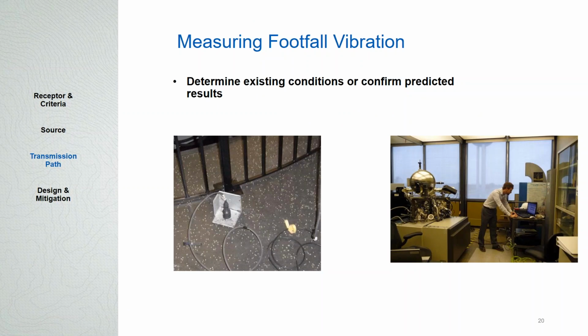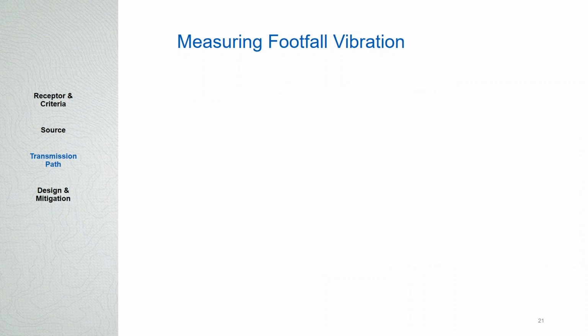And so with that, we show up on site. There are vibration sensors that can measure very, very low levels of vibration, well below the threshold of human perception. Hook a vibration sensor, an accelerometer, up to the data acquisition system and just measure the response that we're getting and see how it compares against the criteria of the equipment or if it's suitable for the lab.